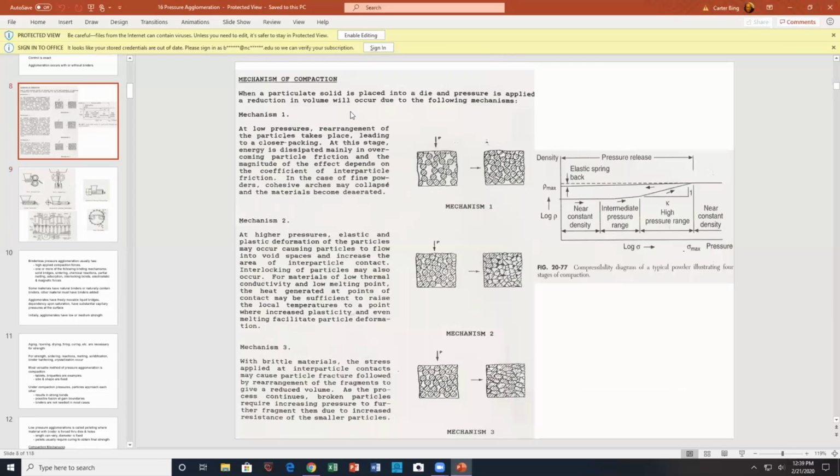Going back to this, the solids are flowing, but you have another phase in there, the secondary phase, the gas phase or the liquid phase, gas phase primarily. Got to worry about how that's going to get out. As you reduce and solidify, densify, you've got to let the air out. If you don't, it will stay in there.